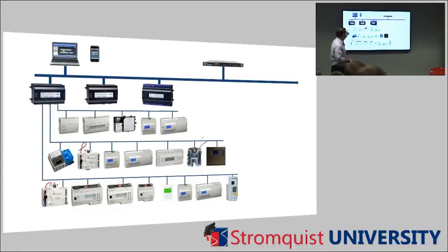So then you just add another Jace, and eventually what we're going to get to is that these would be wired in, and they'd go up here into this supervisor, which is basically like a master Jace, no matter if it's different companies coming in and putting in their products. Well, that's the thing: you've got to have this Jace in that building pulling in all these different communication protocols, and then however many Jaces you need are fine, but those Jaces, remember, they can talk to anything. Does that answer your question?